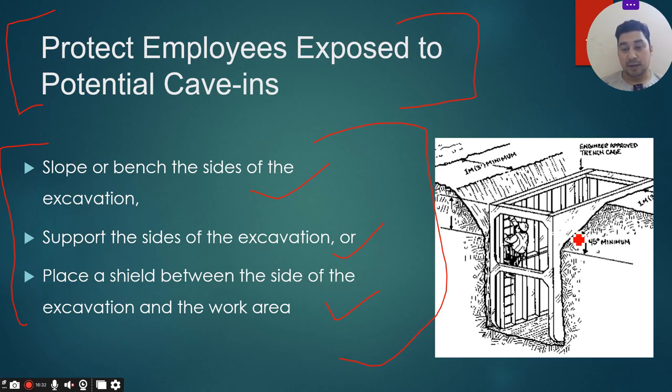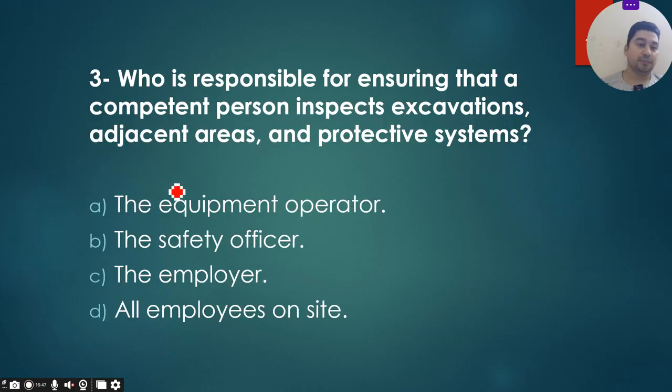You can see here, it is properly protected by the shield and trench boxes, and there is a ladder also properly placed there, and the person can easily come out from here. So this is the way.